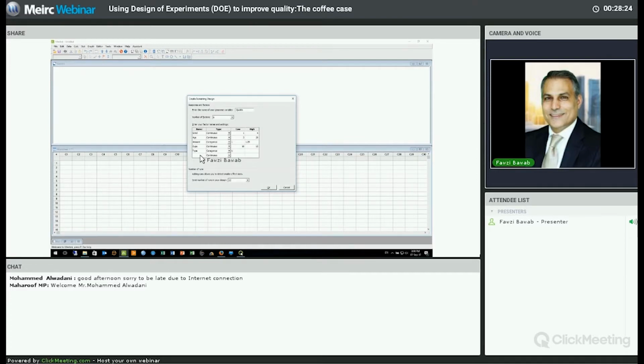What I'm doing right now, I'm using Assistant in design of experiments to help me set up the data collection. Water type, this is category as well. So I could have tap water, or I could have what? A bottled one. Now, once you do that, here it tells you how many runs it will take.